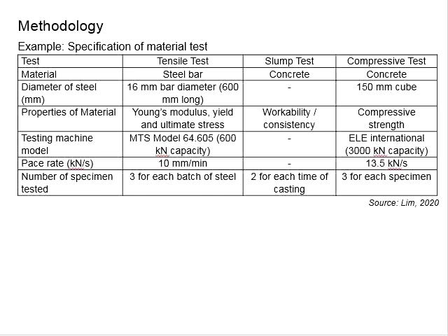And it is also noted that you should not oversize the machines. Let's say now you're using a machine of 2000 kilonewton just to test a sample of 100 kilonewton, which is about 5% of the capacity of the machine. You might have some problem with the accuracy of the measurement, particularly in terms of the decimal place. The load cell built within the machine may not be able to give you accurate numbers to the intended number of significant figures or decimal places.